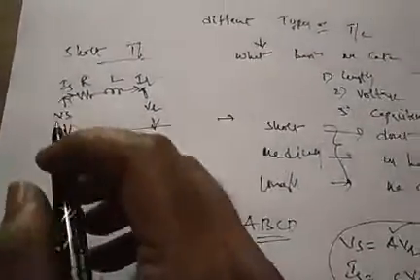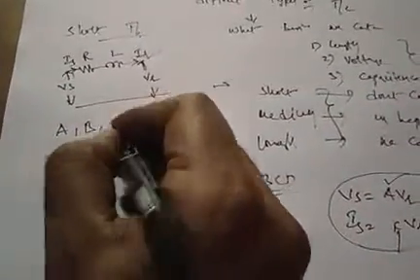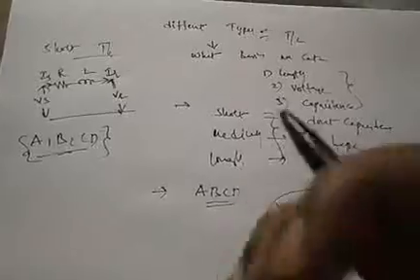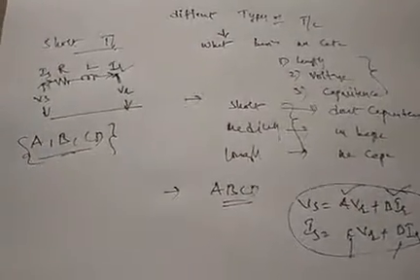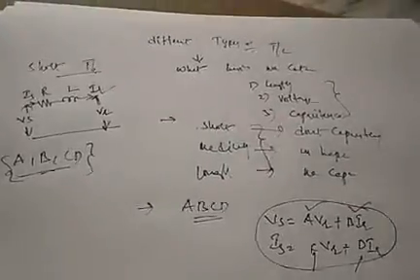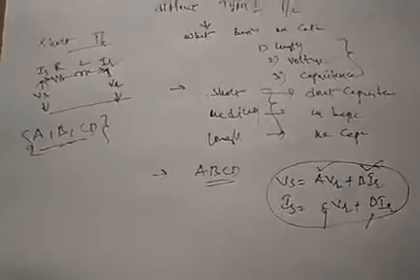We can translate this model of the transmission line into normalized form, and with that you can calculate the ABCD constants. If you know these ABCD constants, they are enough to estimate the performance of a short transmission line. We already discussed this and solved the ABCD parameters for a short transmission line also. And the second one is